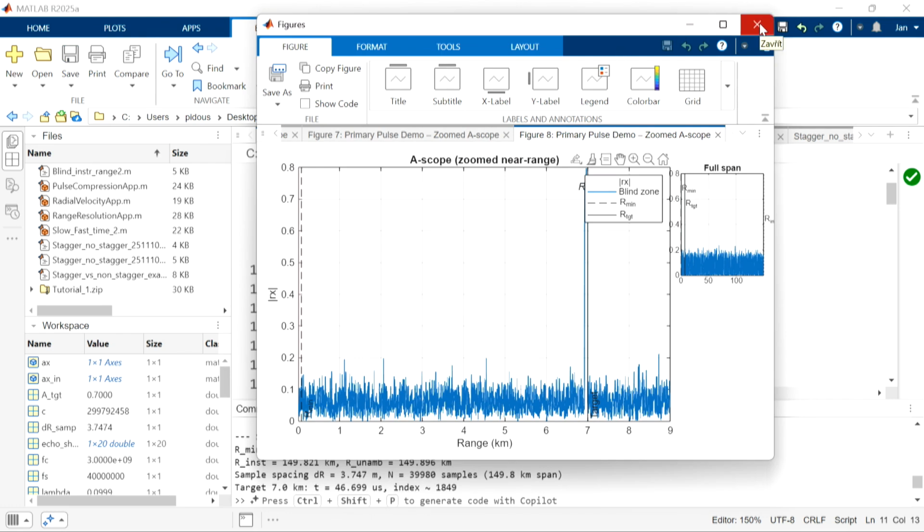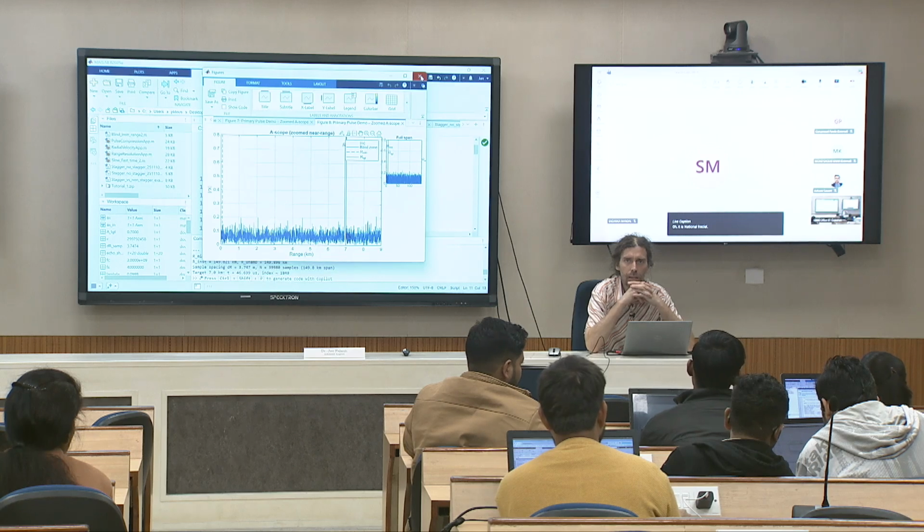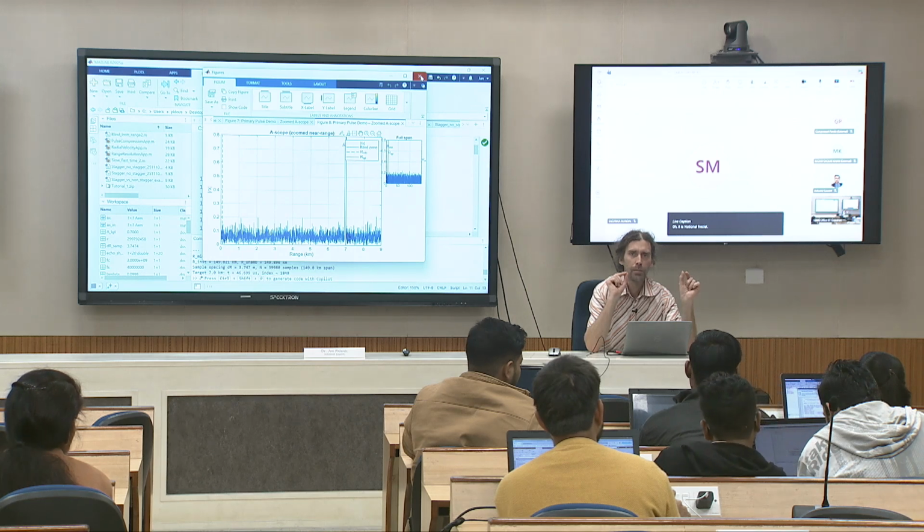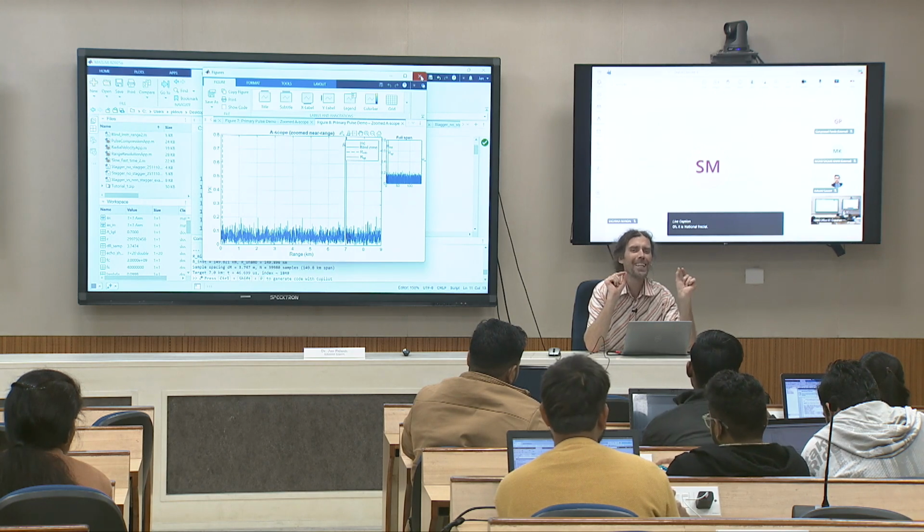Yes? Sir, I have one question. One of the crucial things is sampling rate. It should be 1/2 divided by pulse width, right? It is related to bandwidth. Bandwidth, correct. Be careful, not length of pulse, because if you use some modulation, then it's not tied with length of pulse.